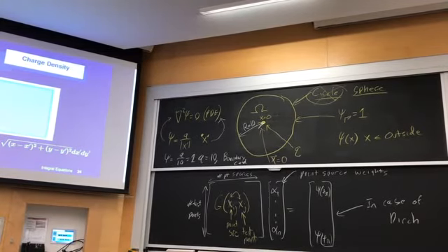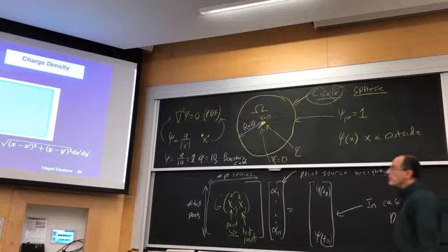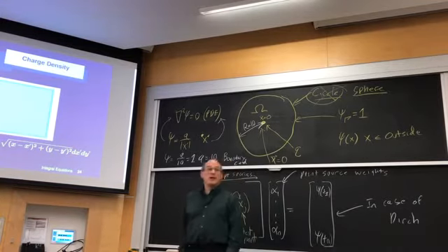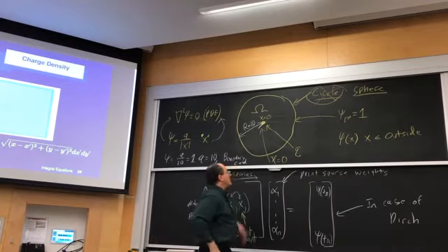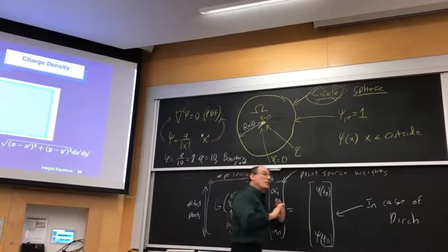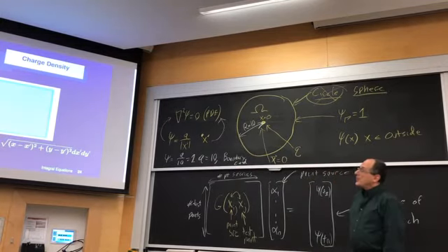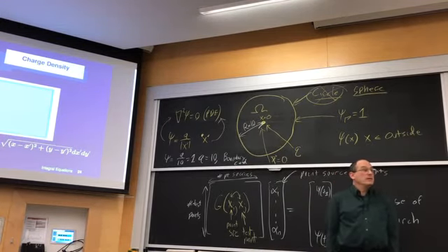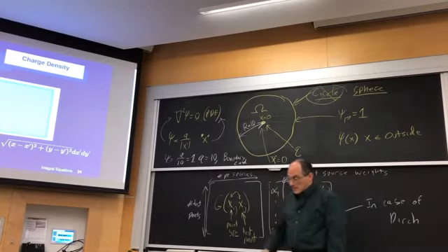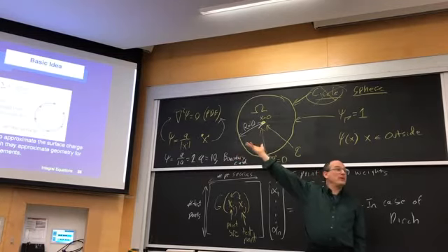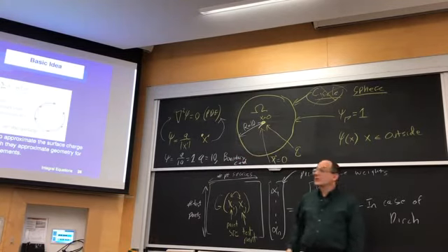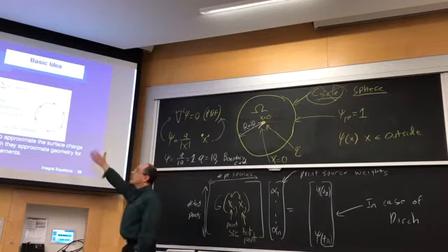Okay, so what's a good representation for the charge density? What should we use? So if we're talking about 2D, what's the surface of a domain in 2D? It's just a line drawn on a piece of paper. It's this curve. Right? So we're talking about this line charge. How should we represent this line charge? It's going to be distributed now. Well, you could use straight piecewise constant charge densities. So these are piecewise constant line charges. This is going to be our basis function.